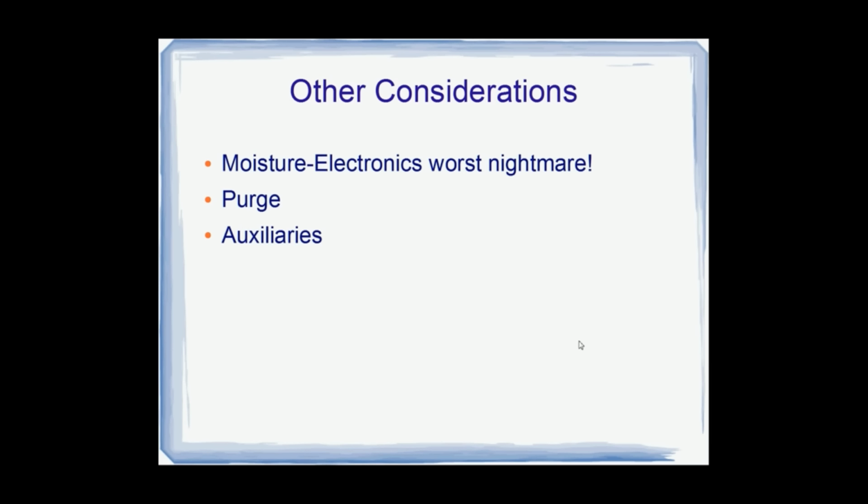So when you run your chamber down to a cold temperature, you're pulling in all the moisture. It acts as a vacuum for moisture, and pulls in all the moisture in the surrounding air around the chamber, inside the chamber. Now when you heat up the chamber, you are going to have moisture condensation all over your test hardware.